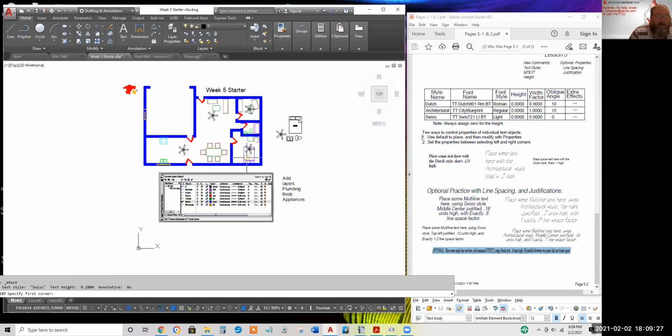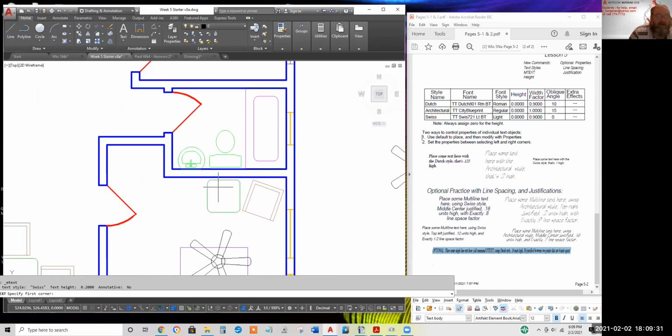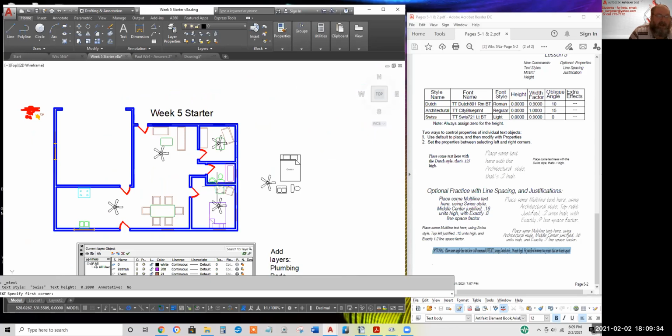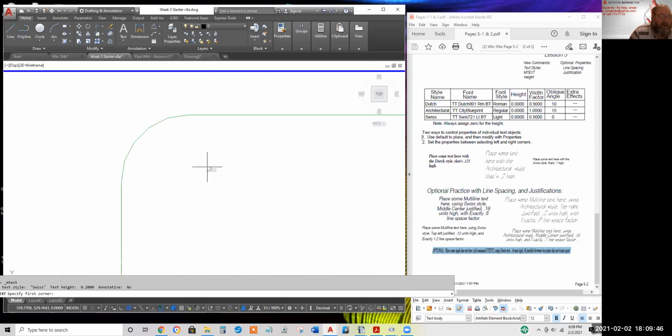By the way, this is going to come out microscopic. So I suggest zoom in on an end table if you still got one in this bedroom. And it'll occupy just a corner of this end table. Remember, an AutoCAD unit is an inch now on the floor plan. Anyway, pick your first corner, in other words, the left margin. And it's tempting to come over here and eyeball the right margin.